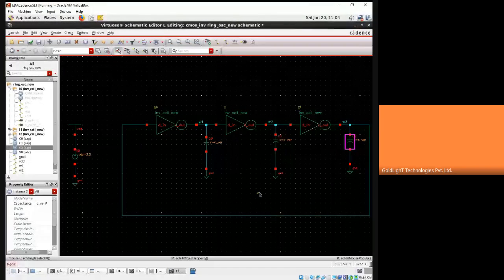and one more very important thing is, you have to always connect an odd number of inverters. I think you know that, right? Only then will you get the waveform. Otherwise, you will not get the waveform. That is a very important thing. Okay. Now, we have given the name like this.